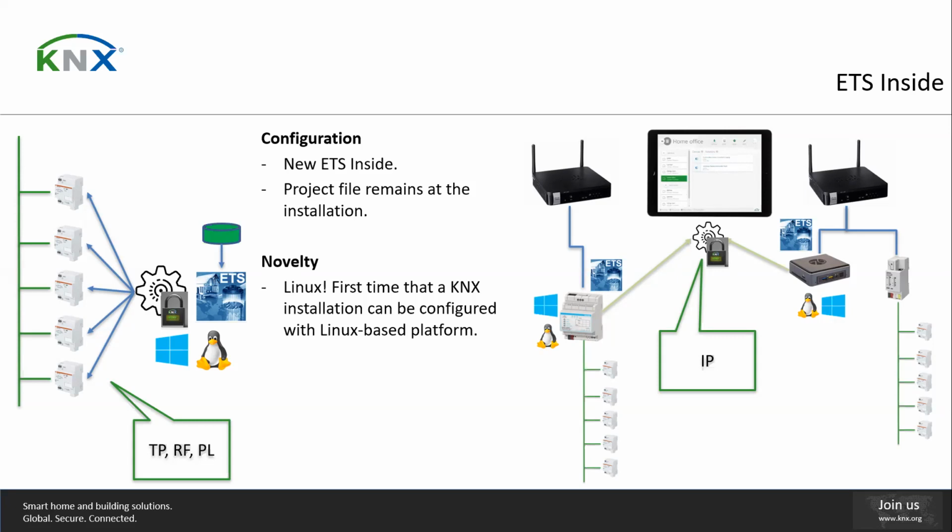So this is important because it allows KNX to go more into the smart home market. And the difference is that the ETS software now is not sitting on a computer of a system integrator, but is sitting inside the installation. So it remains in the installation on site, and it also keeps the configuration files on site. And this server, ETS Inside server, offers a user interface for configuration and commissioning. So you can connect with any Android, Apple device, or Windows tablet and configure the installation.